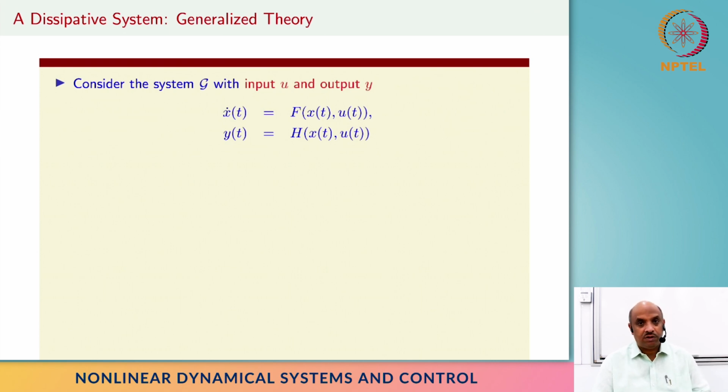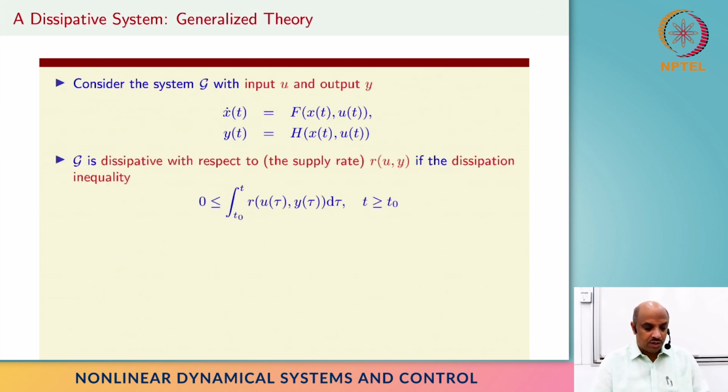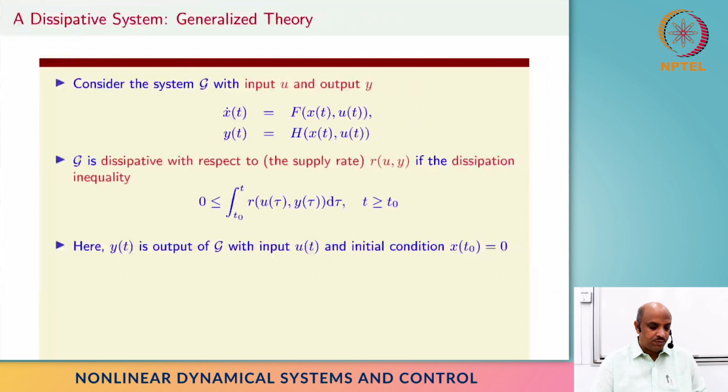The conclusion is basically we have a Lyapunov function if we have a system that is stable, right? So here the definition of dissipativity itself is directly in terms of quote-unquote Lyapunov function, or specifically the terminology we use as storage function, right? So can we actually define dissipativity without ever talking about the storage function? The answer is yes, and it turns out quite interesting, and there's equivalency between many of these concepts, right? So Willems basically therefore defined this concept called dissipativity with respect to a supply rate without ever talking about storage function.